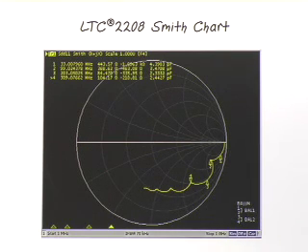What is not shown here is the current pulse that results from the switching action of the ADC's sample and hold. The other thing to remember is that your matching network will also be part of an anti-aliasing filter. So you need to do several things. Settle within half a clock cycle after the current pulse. Design a filter that meets the requirements and not load down the amplifier so much that it adds distortion, and match over the entire frequency range of operation.